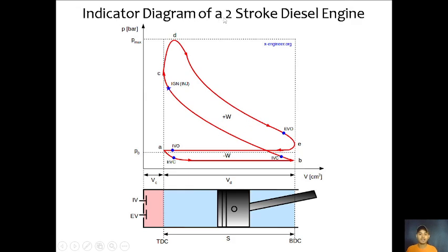So this is an indicator diagram of a 4-stroke. Sorry for that mistake. So it's a 4-stroke diesel engine. Let's start here from letter A. As the piston moves down, the intake valve opens. Going down here, and then when the piston moves up, it starts its compression. On this point, the intake valve closes, and then compression starts.